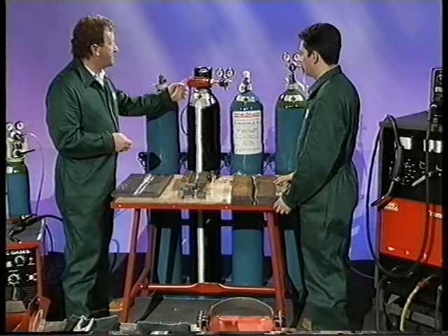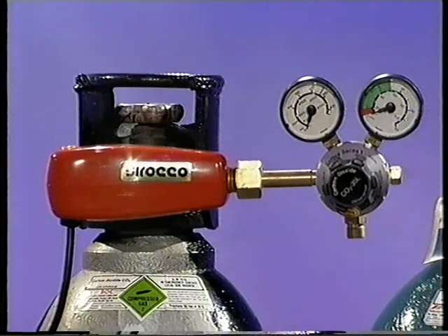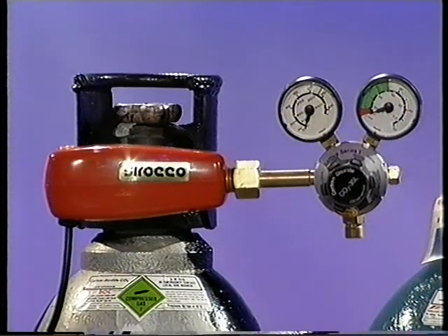It has to be heated before going into the regulator to prevent freezing. It produces quite a lot of spatter when used in the weld, and also for thick section weld, it won't achieve spray transfer. Right, so things moved on.